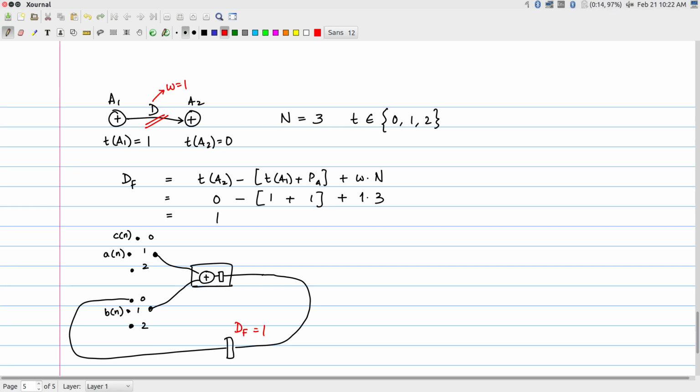Okay, so if we write out the time sequence saying these are the time instants at which the different A of n, B of n, C of n values are being generated and applied over here, correspondingly everything will change. Of course, you need to keep one thing in mind. I arbitrarily did one pipelining step over here. That is to say, I inserted one iteration delay between A1 and A2.